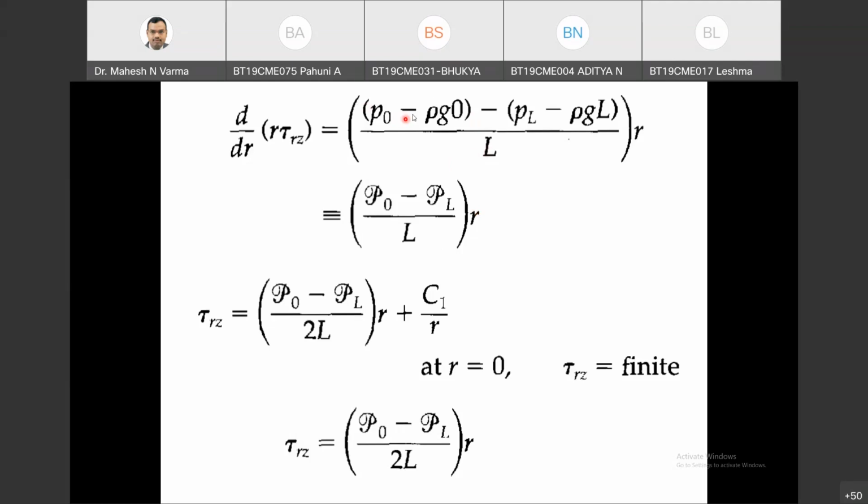Excuse me, sir. Yeah, tell me. Sir, this doubt is about Vz. We are saying from the continuity equation that Vz is not varying in the Z direction. But from the continuity equation, we can only comment on average Vz, right? No, from the continuity equation we can say average velocity into rho into area. No, that is not average velocity. That will be the local value actually.